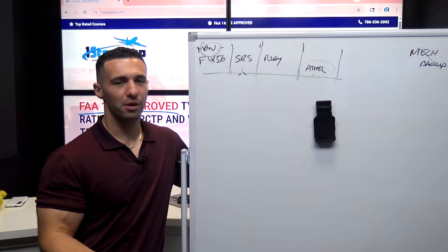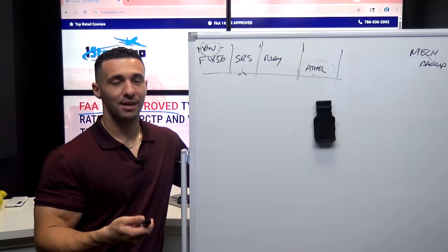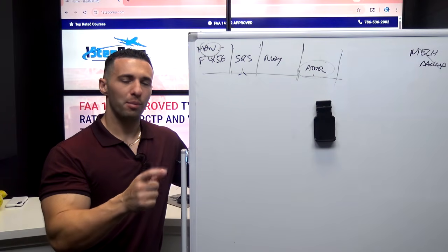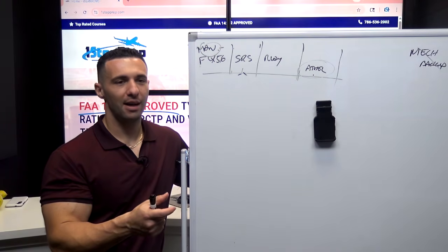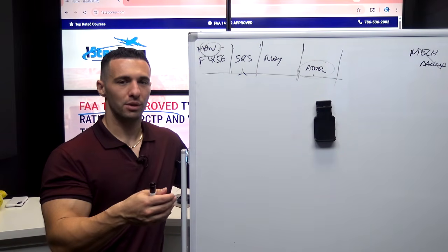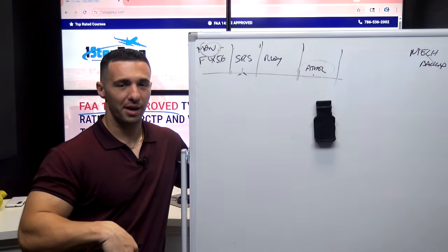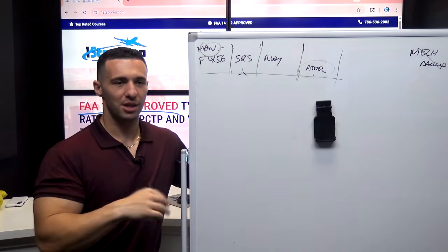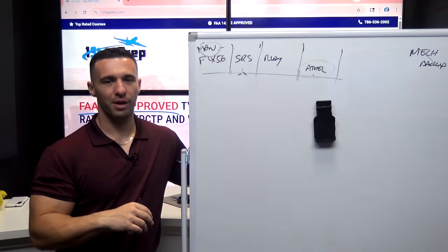And then some other variables would include, am I high, and are they going to dump me down? If all these are lining up where you're kind of high, you're going to need to get down, then usually I'll just throw flaps 2, which will allow me to use the spoilers right away and not have the VLS shoot up to an uncomfortable position and potentially get closer to the alpha prot.